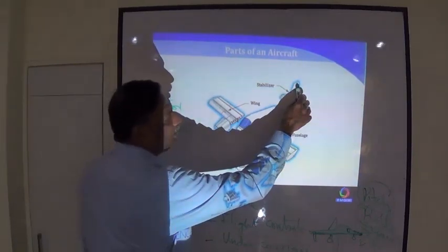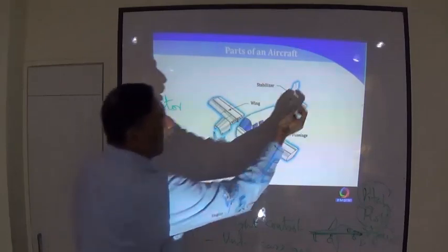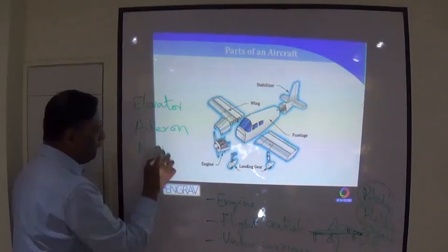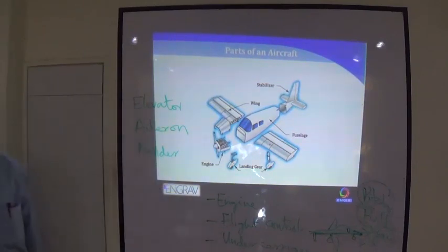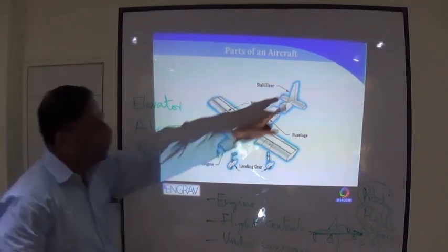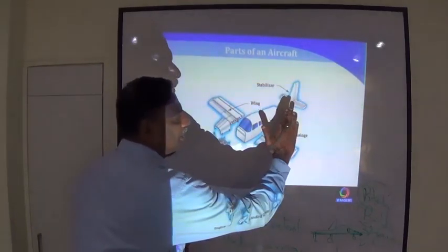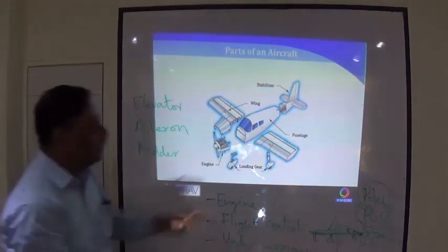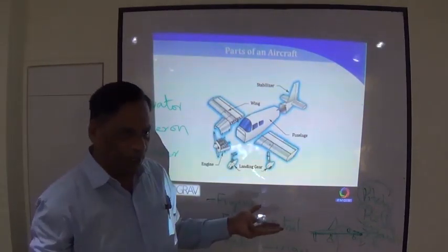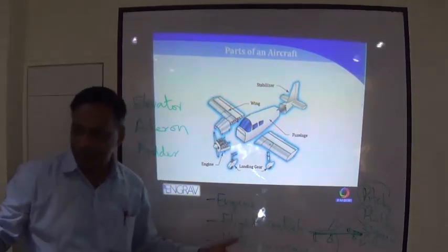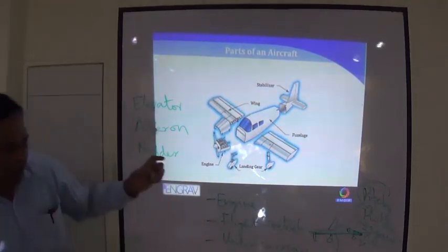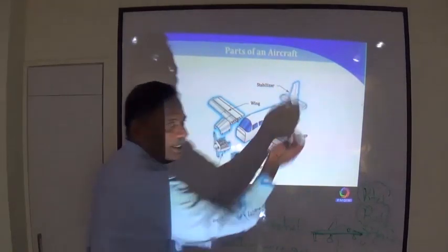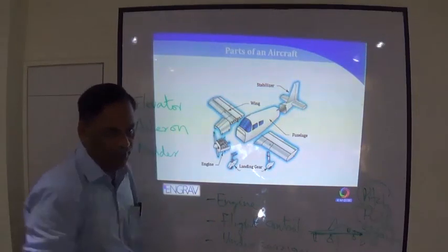This is called vertical stabilizer. On the vertical stabilizer, you have something called rudder, R-U-D-D-E-R. So you turn the rudder this way, so you have a lift getting, everything is related to the lift. Because the airflow is freely available, I manipulate my position in such a manner that I create lift or drop the lift, then I get it. So if I have a lift going that way, my nose will turn left.